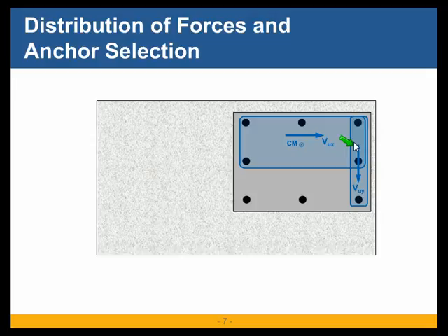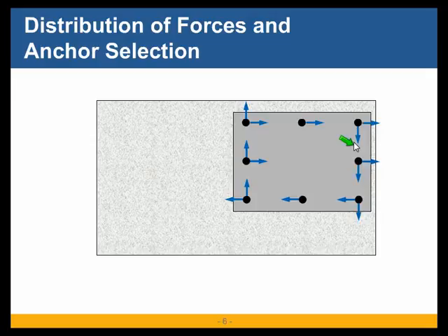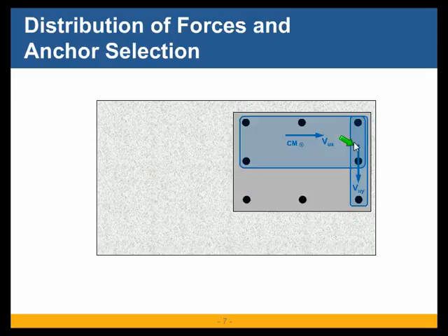So you can see that even though we have a same set of anchors, the tension analysis is being carried out on these three anchors, and the shear analysis are carried out for x shear, these 5 anchors, and for y shear, these 3 anchors. So it could always happen that different subgroups of anchors are being used for tension or for shear analysis, which is completely fine, and that is what Appendix D requires us to do.